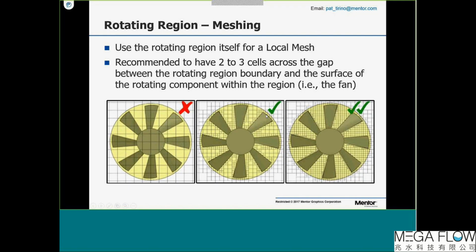Again, here, this is good. This is a good representation of the mesh where we're doing some local refinement. This one's even better, okay? Obviously, it's refined to one more level than the previous one, and I would probably make it more uniform across the blade. So in other words, you can kind of see here the level of refinement changes. So I would almost grab the end of the blade and make it more uniform in that region at the outer perimeter, okay?